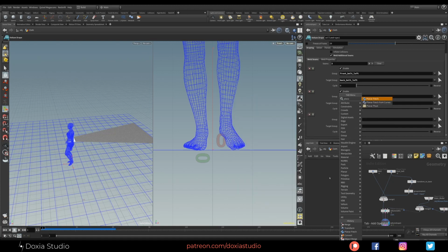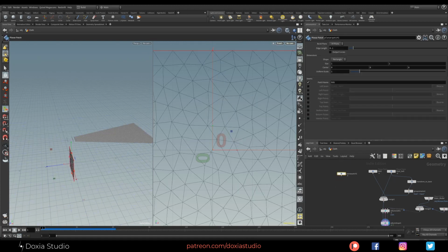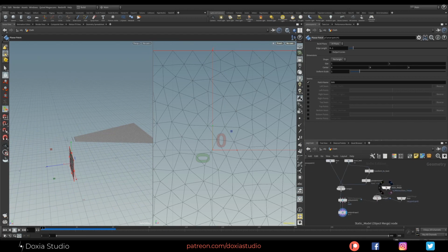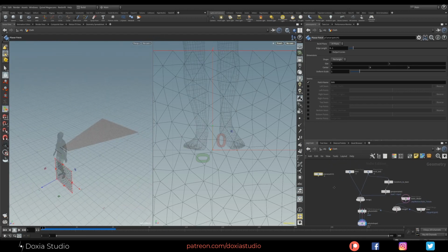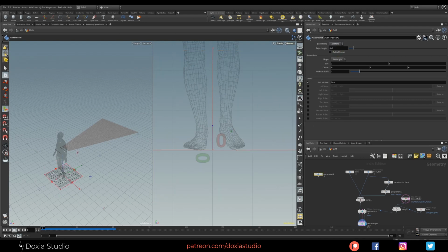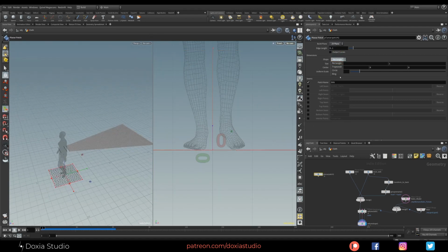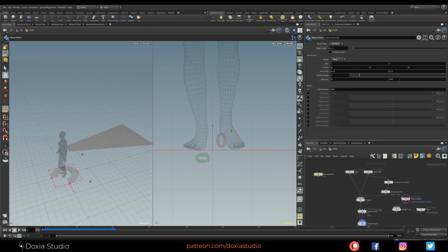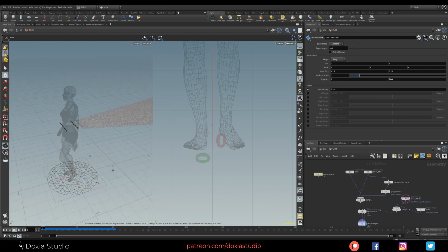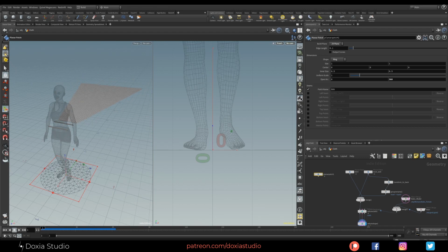Let's use again a planar patch. I need to see my model. Okay. I want this on Z and X, and on shape we are going to use ring. We don't want an open arc, we want a closed arc. But I don't know why, if we increase this to 360 angle, you see that our planar patch is now closed. It's not a ring, we don't have a hole inside.